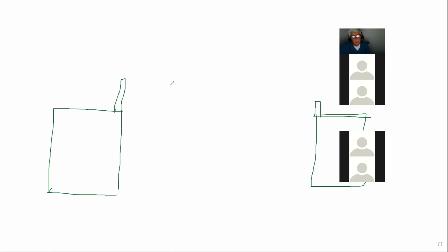He's going to short a wall here, and he has this beam in here. Okay, got it. You see, and it's going to be doing this. And to get him the lowest size, I even calculated for him to laterally brace the beam so they can minimize the size of the beam, and came up with a very easy solution.